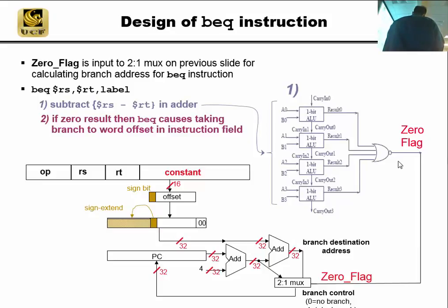Sometimes it helps. So here we're going to wire this up so that when a 1 comes in, we grab all the bits. This is many to 1, right? We grab all the bits that are on this right side. This is the 0 and the 1 data input. Then when the select is 1, we take the branch. How do we do that? Well, we've taken this offset and added it to the PC. Right here, we add it to the PC.